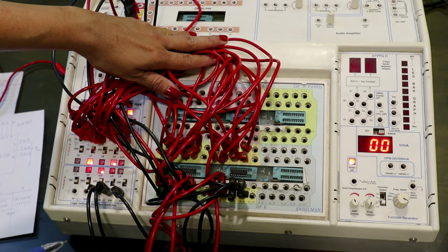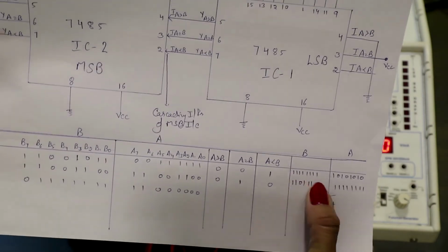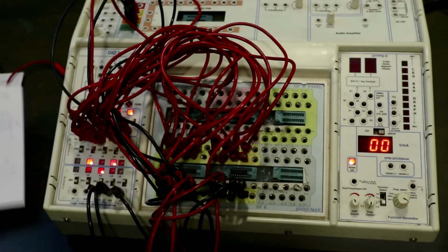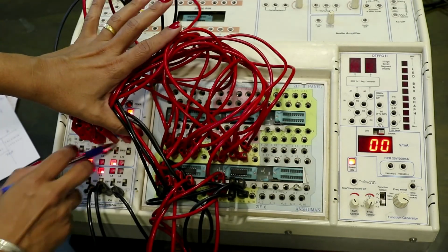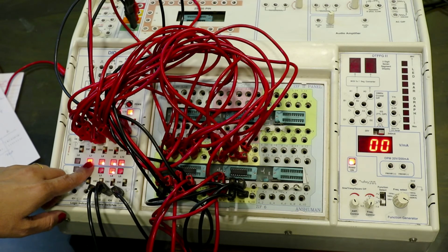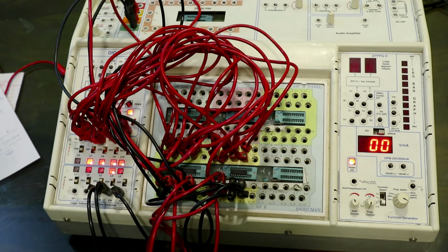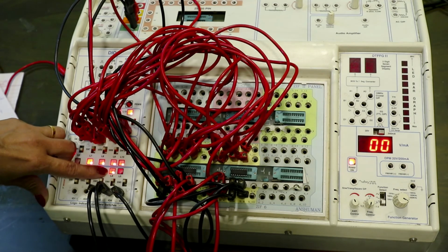So when you consider an input for B as all 1s and A as 1 0 1 0, in this case I know B is greater than A, so that's why for the output your last combination is high. Okay, so in a similar way you can test any combination on this board. Suppose I want to keep all 1. Now all are 1. B is already equal to 1, right? So if A is 1, all digits from A0 to A7, and for B, B0 to B7, all digits are 1, our output should be A equal to B. So the middle one is the output for A equal to B. So this LED is glowing.